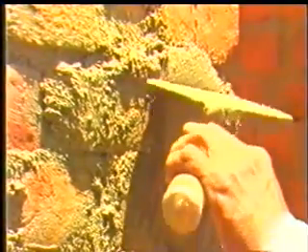Before applying cement mortar, the walls are wetted with water. Thickness blocks are prepared on the wall for proper thickness and surface finish. The mortar is then applied on the wall and finished with hand tools.